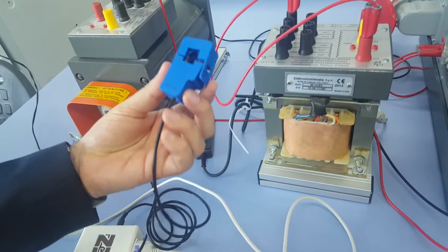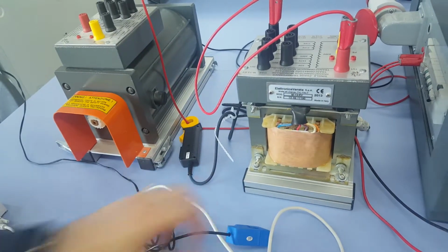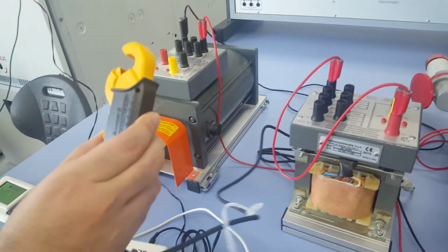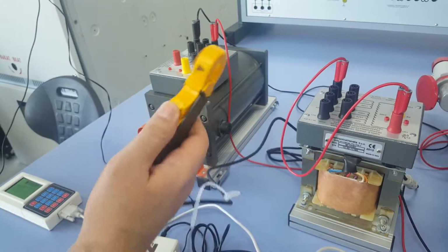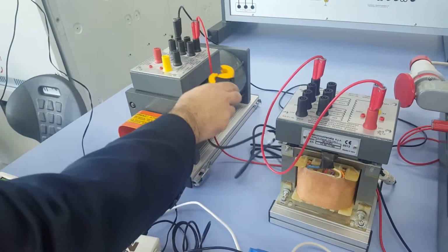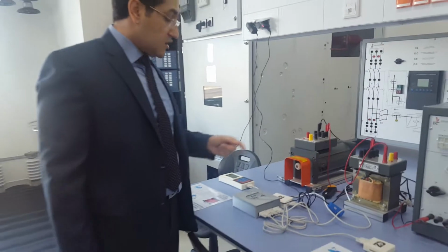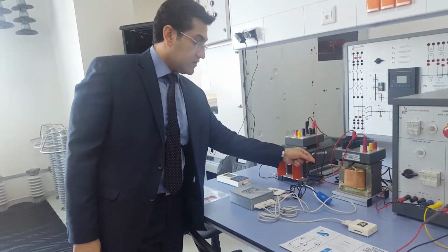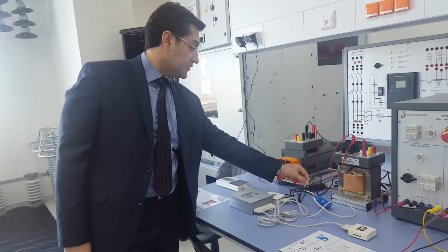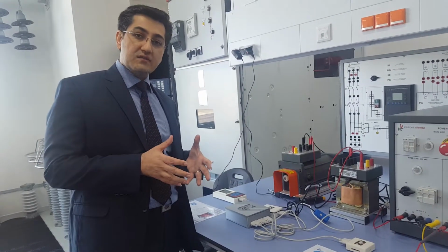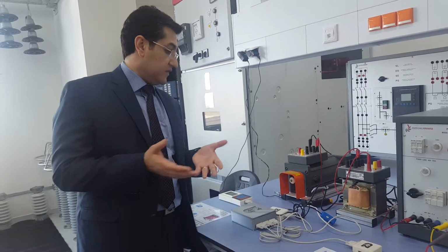We have used, this is very simple, a tiny CT. Or if the current is getting a little bit larger, we can change the CT. When we are changing the CT, it's simply possible to grab the information from the current which is flowing through your feeder or through a cable. So you can adopt any kind of clamping CT or clamping ammeter with the system. Therefore, the system is designed to serve from 400 volt or even less than 400 volt up to, let's say, 1 million volt. It's not a big deal.